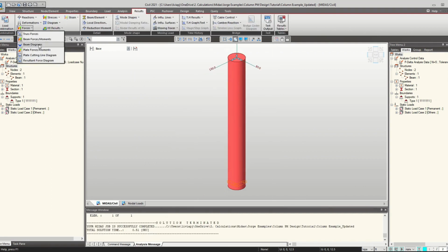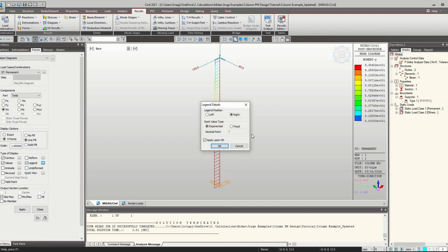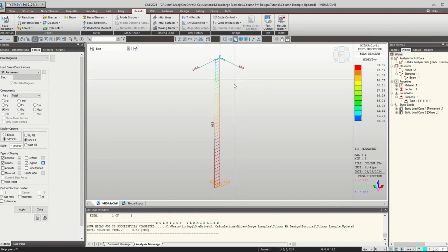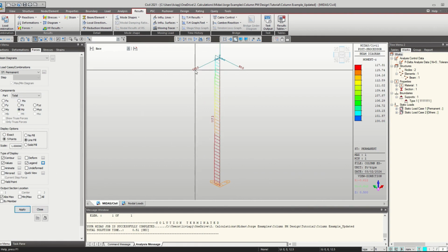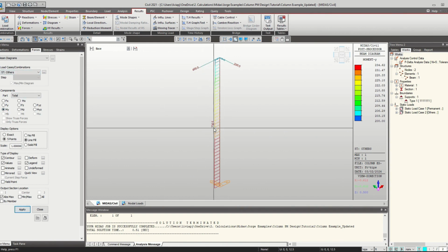Our results, forces, beam diagrams, and let's just individually see each load case first. Let's click values, legend. Let's update it to be fixed, not scientific. And here we go. We see that our applied was 80, and now the magnified is 93.80. Let's check the other direction. It was 100, and now it's 117.3. Others really quickly. 600, now 703. And in the other direction, 200 to 234.